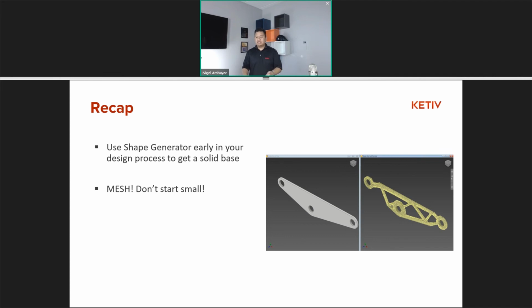It's pretty bad. I had a simulation running on my computer for 30 minutes that just blew up because I decided I wanted to start at 0.8 instead of 3. So don't do that. Use the mass reduction tool in regards to percentage to go ahead and control that shape, or a mass target. If you wanted to get to 50 pounds, say, 49 pounds.